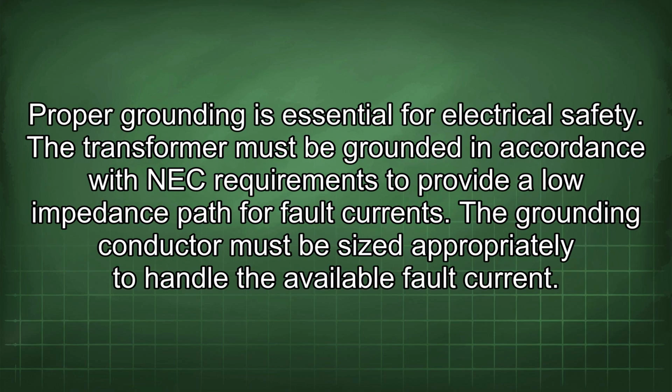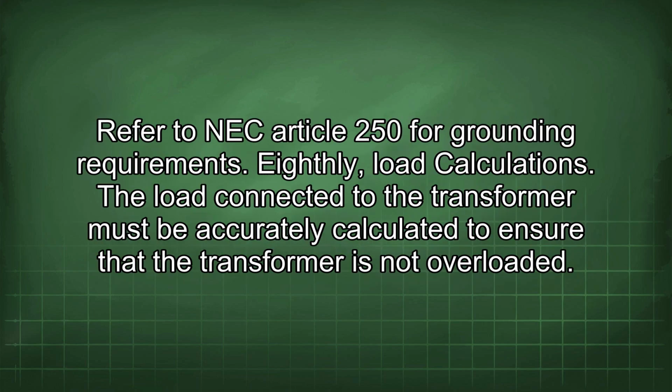Proper grounding is essential for electrical safety. The transformer must be grounded in accordance with NEC requirements to provide a low impedance path for fault currents. The grounding conductor must be sized appropriately to handle the available fault current. Refer to NEC Article 250 for grounding requirements.